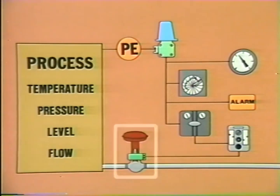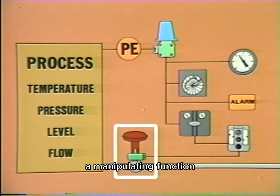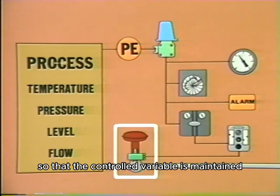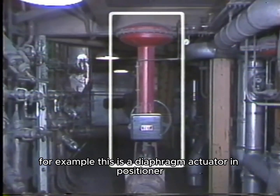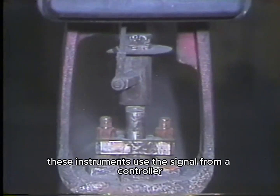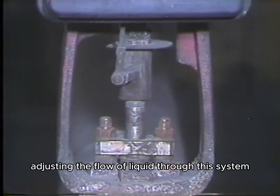However, under normal operating conditions, the controller's signal merely passes through the control station on its way to a final control element. Final control elements are instruments that perform a manipulating function. They manipulate a process variable in some way so that the controlled variable is maintained within a desired range. For example, this is a diaphragm actuator and positioner. Together, these instruments use the signal from a controller to position a valve, adjusting the flow of liquid through this system.